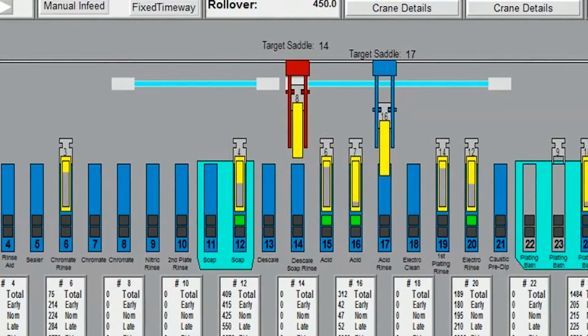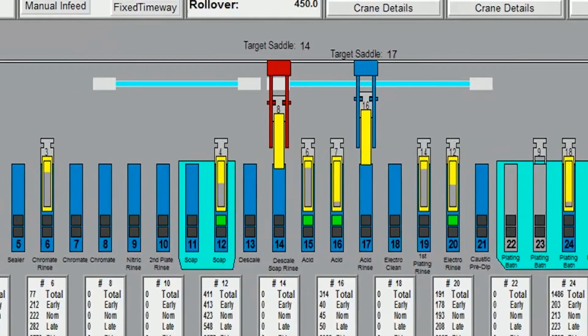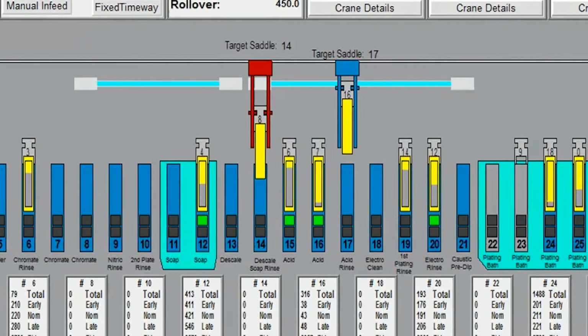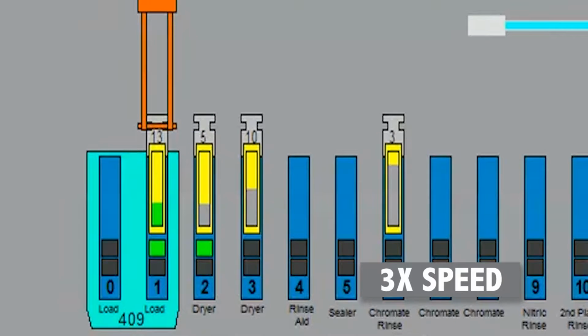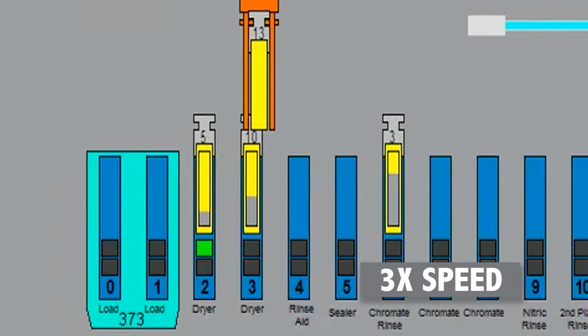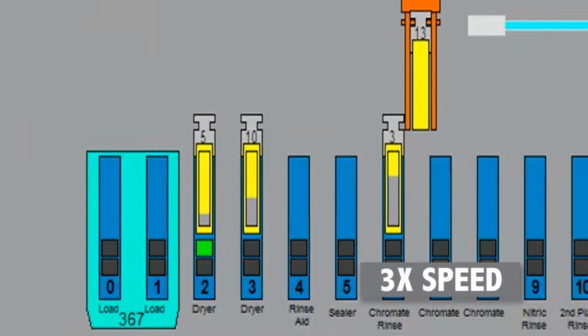Cranes monitor all the loads in the space they are responsible for and select the highest bidding load for the next crane move. The destination for the move is specified by the load and comes from the recipe, which is carried by the load. Cranes constantly monitor the loads in the line and respond to requests for transport by accepting the highest bid. This system ensures that the most important move is always selected.